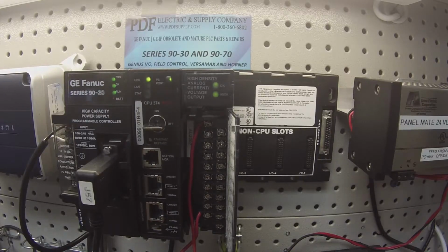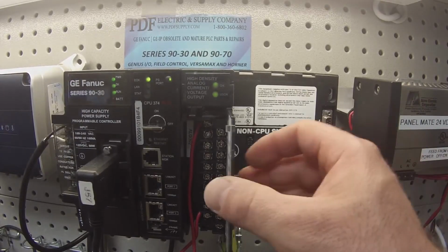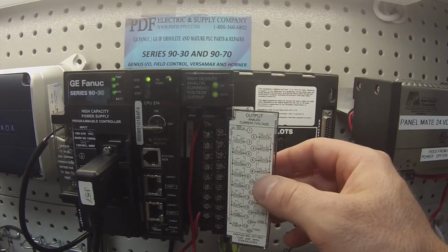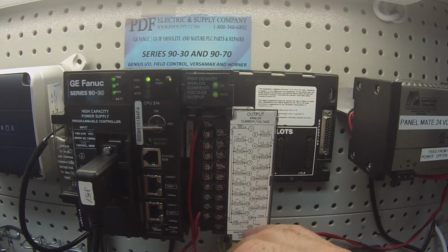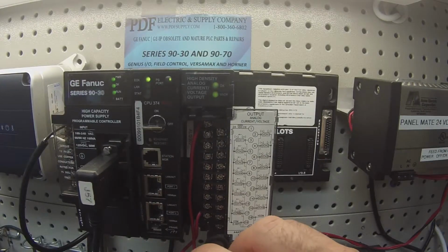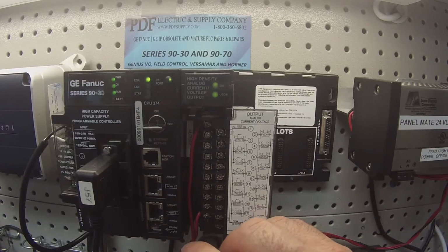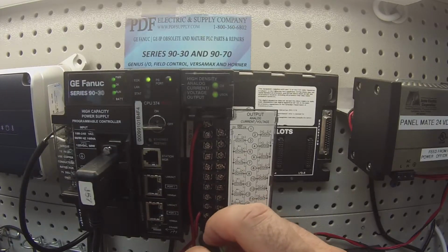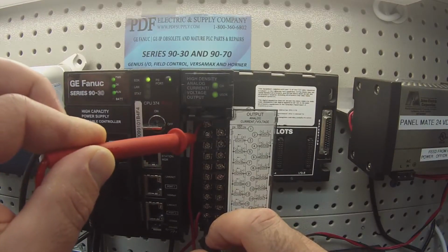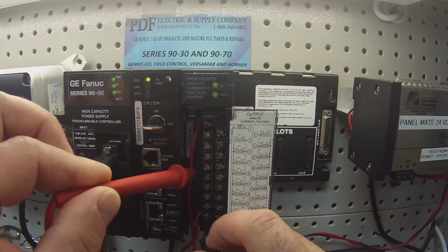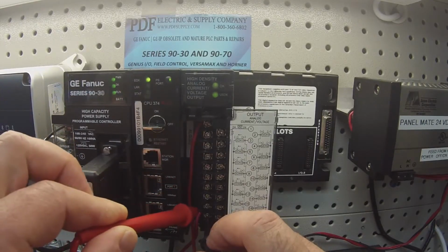And I do the exact same thing with the milliamp side. So as far as testing the milliamp side, it's the same exact test that we just did for the voltage. The only difference is you'll have to set your multimeter to read milliamps, and the common in this particular case is the same common as your power supply. So you'll take the common and put it on terminal number 19, and then test all of your corresponding channels from terminal 3, 5, 7, 9, all the way through 17.